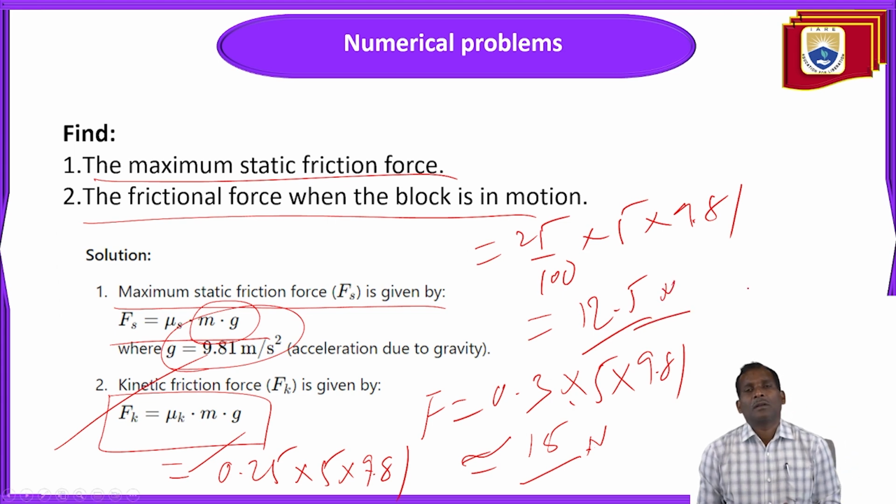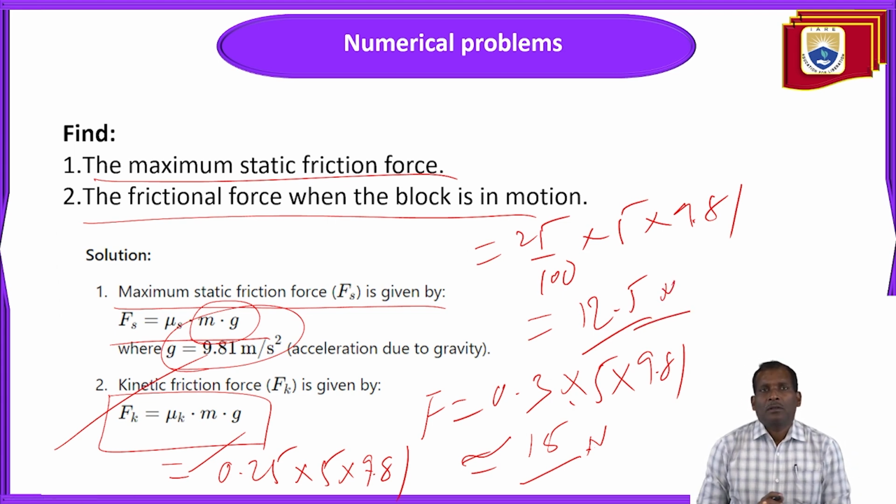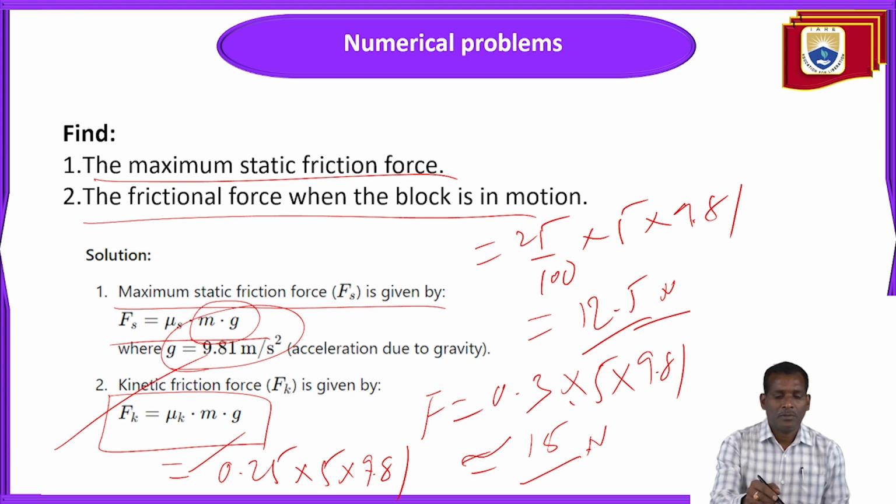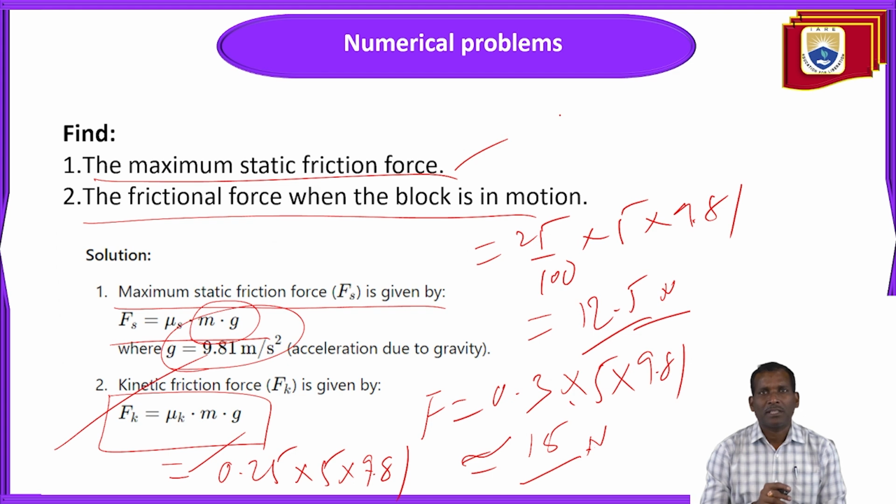Clear? So the frictional force is reduced when compared to the static frictional force. We have calculated the maximum static frictional force and the frictional force when the block is in motion. Like this you need to calculate.